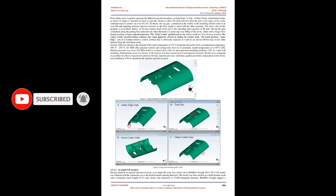14. Sridharan et al. 2018, worked on the prediction of molding defects and achieving optimized process settings by applying response surface methodology, RSM. Moldflow was used for flow simulation to ascertain possible molding defects and initial process parameters. RSM helped in identifying relationships between various process parameters and performance. 4 process parameters, injection time, holding time, filling time, and mold closing time, were considered for the study, with the output being the cycle time.